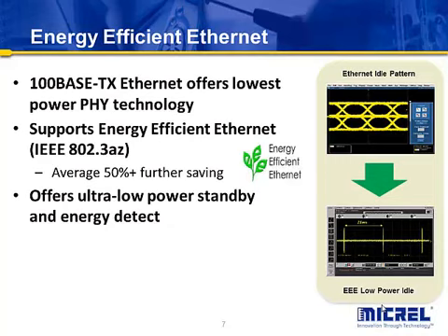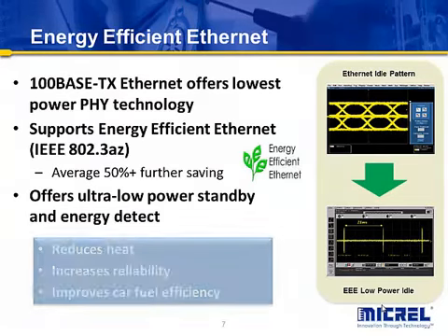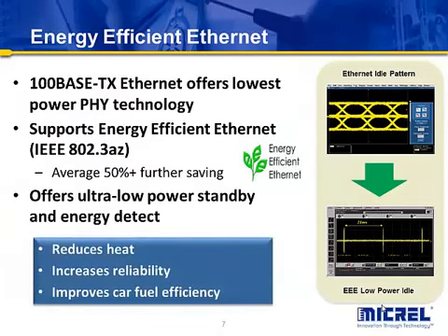Standard Ethernet PHYs can also offer ultra-low standby currents for automotive and wake up on signal detection for remote powering. In conclusion, standard Ethernet reduces heat and hence increases reliability and fuel efficiency.